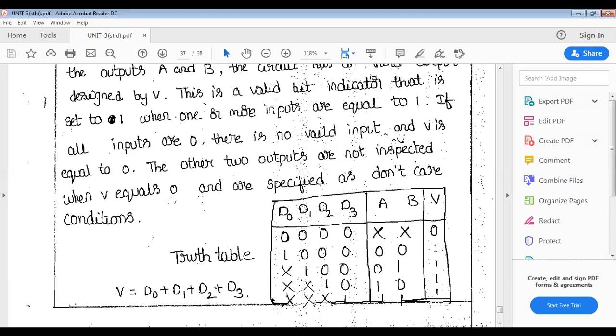bit on the output side, whatever we represented in the design, the value is 1, 1. Okay, for 0, 0, 1, it is a 1. And now D0, I take it as a don't care, meaning it is either 0 or 1, since one or more inputs is 1 here. And here also you can see 1, 0, D2 is high, and D1 and D0 are represented as don't care. Don't care means we can't say it is a 0, we can't say it is a 1. Again, on the input side there is one or more inputs. Similarly, there is a don't care here.